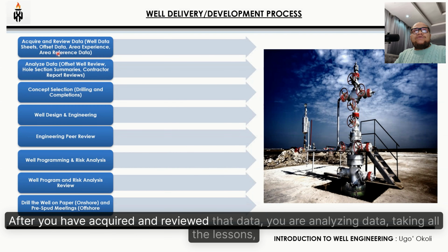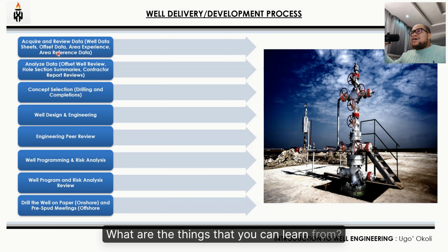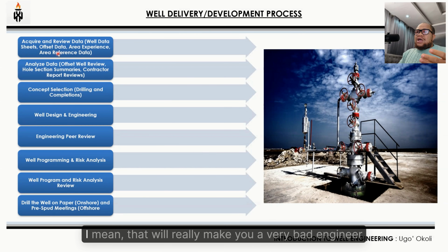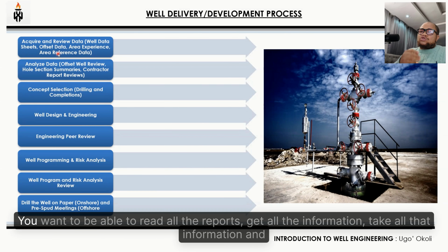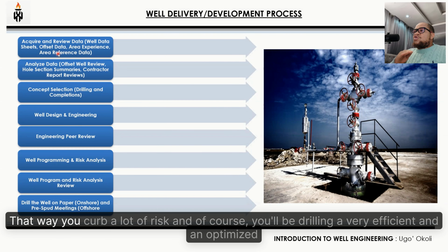After you have acquired and reviewed that data, you are analyzing data, taking all the lessons, taking all the hole section summaries, taking all the contractor reports. What are the things that you can learn from? Because you don't want to come on a new well and relearn a lesson that's been learnt before. That will really make you a very bad engineer. You want to be able to read all the reports, get all the information, and put it into the new design. That way, you curb a lot of risk, and of course, you'll be drilling a very efficient and optimized well.